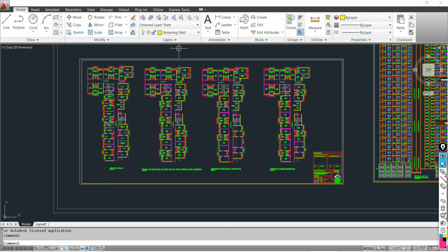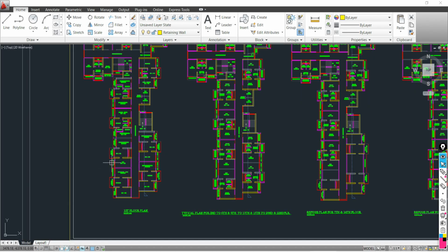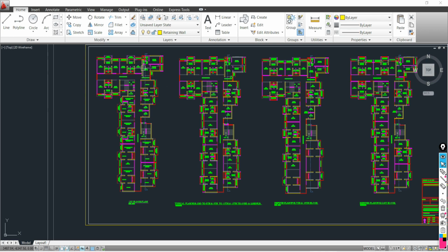See the geometry. Is it possible? Actually, you don't know because you have not worked on this kind of project. But it is not possible to prepare the grids for this in ETABS itself. You have to prepare the grids in CAD by center line plan, and then import that in the ETABS software.